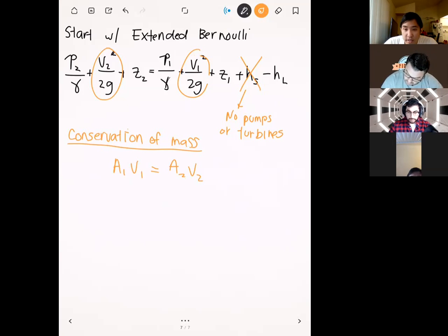So there's a question in the chat. Did I say that this Bernoulli form was head form? Yes, that's correct. This is the head form of the Bernoulli equation. So you divide everything by, I think, gravity and rho, and you get everything in units of length.